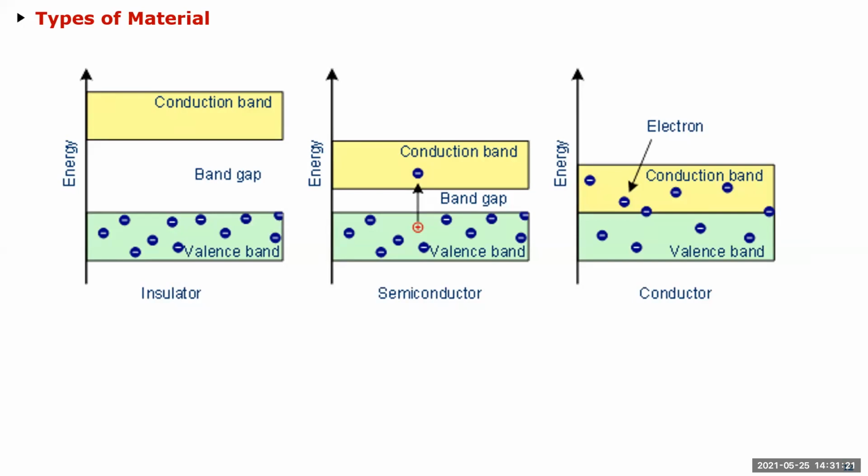And because it's so thin, the electric field is voltage divided by distance, right? So if you have a given voltage and you keep reducing the distance, then the electric field just becomes bigger and bigger. So that's why the breakdown voltage for those transistors is lower and lower as the oxide gets thinner. For example, in 1 micron technology, the voltages were 5 volts. So you could almost apply 6 volts to the gate and the oxide would be fine.